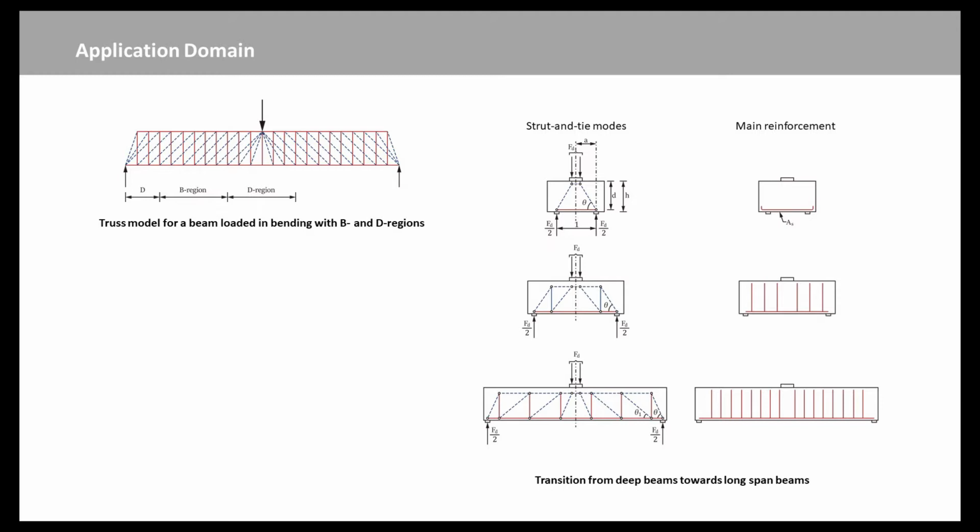The philosophy described above is the one of the lower bound methods for plastic design in ultimate limit state. According to the lower bound theorem, the structural member doesn't fail for the imposed load combination if a stress distribution can be identified for which equilibrium is guaranteed, and the threshold for plastic behavior of materials is not exceeded.